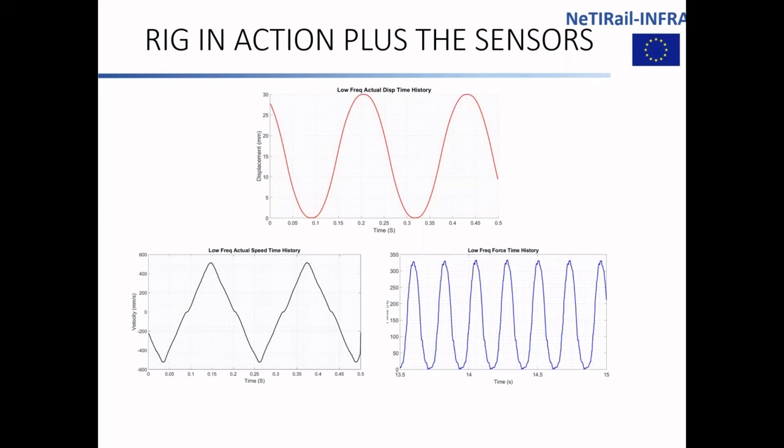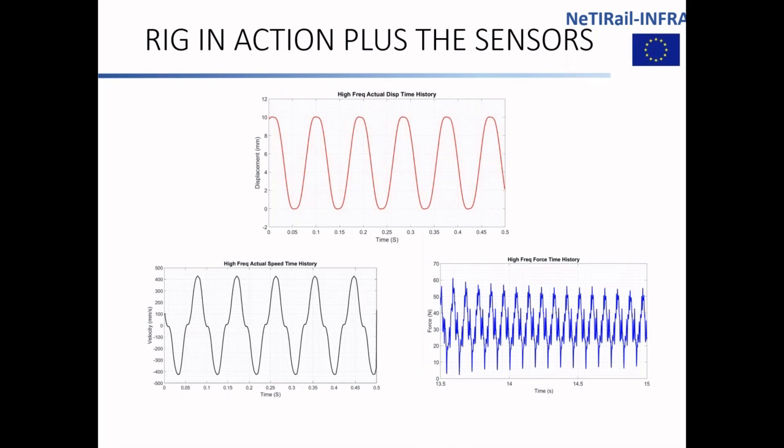This was very interesting, that we could take the waveforms from the actuator and compare them to the acceleration data from the 2DAS sensors. It gave us some really interesting results as well. You could see some of the additional frequencies that we got on the catenary wire, but also as you stopped the actuator, you could see the natural frequencies of the overhead line.